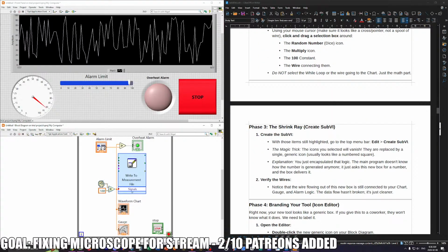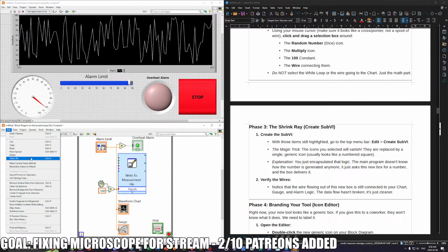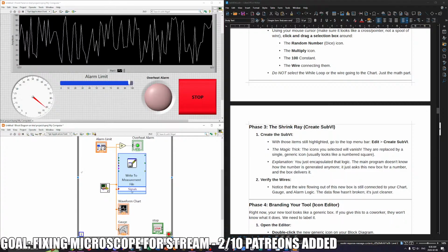Okay, the shrink ray, create sub VI. Go to the top menu, edit, create sub VI. I keep saying IV, but create sub VI. Here we go.